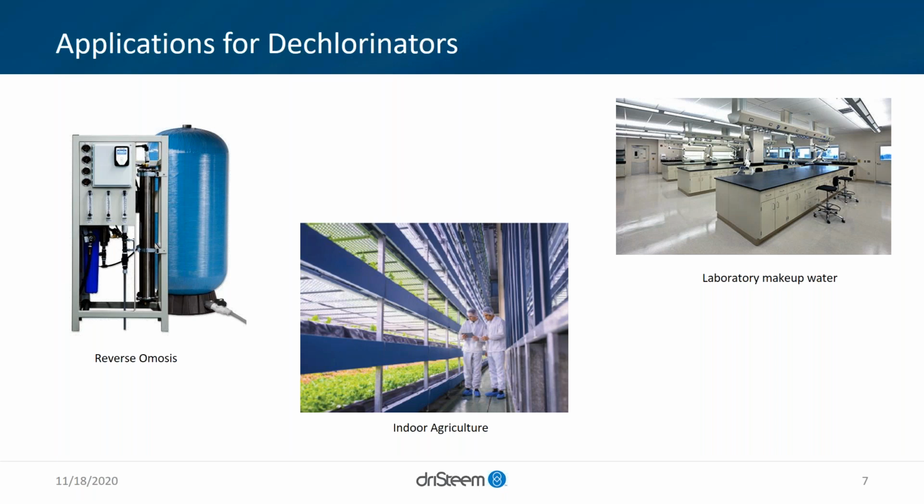What's bad about the water quality going down, you may ask? Well, your investment goes down, but really why did you get the RO in the first place? Now, if we're talking ROs for humidification applications, the water quality that we're expecting to get at, let's say, a GTS LX is hypothetically 10 ppm of RO water, TDS. Over time, it'll go to 11 to 12 to 13 as that membrane breaks down. That can have a negative effect in the sense of what you're trying to prevent with water treatment is going to happen because you're sending poor water quality downstream.